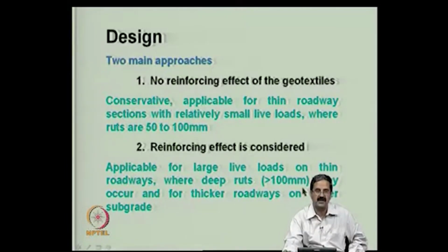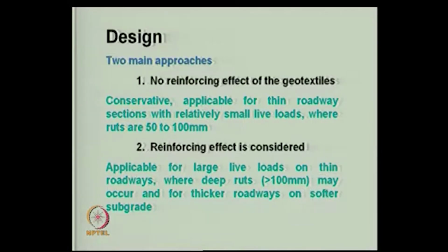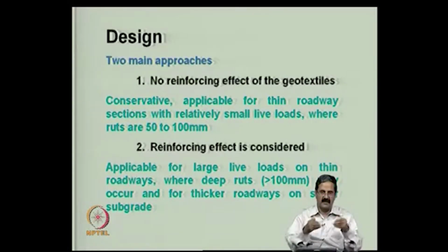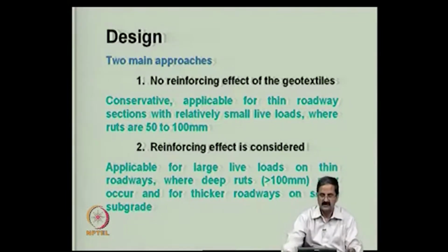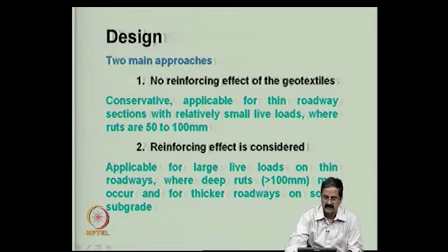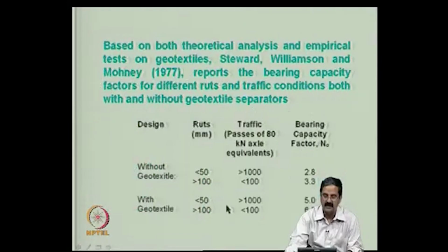Like as I just mentioned, the rutting depth, the membrane effect. Membrane effect is there. The higher the depression that you have, the higher is the tensile force mobilized. So, if you want to really handle higher depths of ruts, you need to have higher tensile force, and you may consider thicker roadways on soft grade and all that, right.